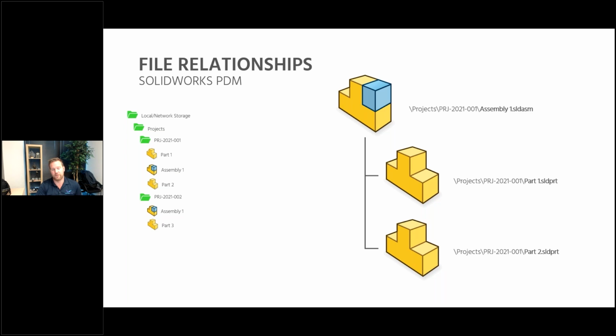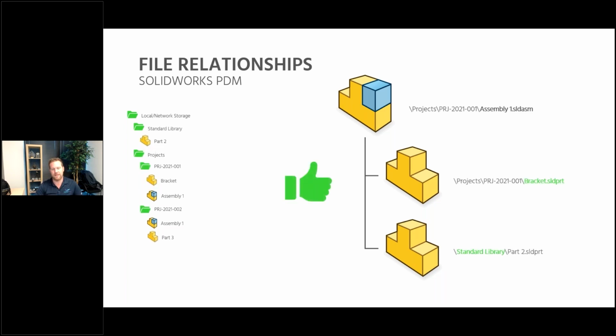It uses SQL Server as the database. It has an archive server where it actually stores those files, and it stores the file path, location and name as metadata of a record, think of it as a row in SQL. So using PDM, we have full capabilities to move and rename all of these things, and everything is remapped appropriately. So we have full flexibility to do whatever we want, make sure our data is organized and appropriately named for what it should be, as well as all the correct metadata, information or properties about those files, without having to worry about managing all those file references.